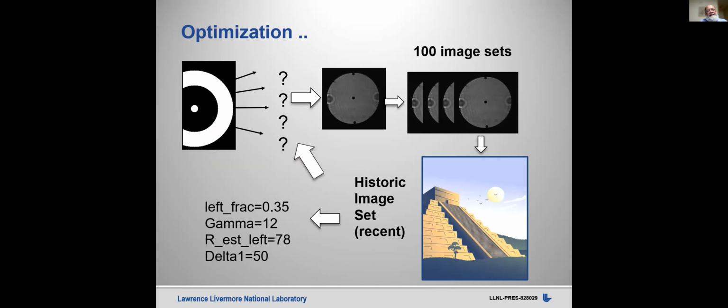Now, since there are 4 parameters, what we normally have to do is an optimization to select these 4 parameters. So normally we have an image set of 100 images taken in an aligned position, and we run through all these images to see if it can detect at the correct location. It gives us a set of 4 parameters, as shown in the lower left.